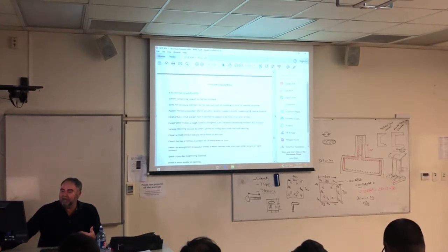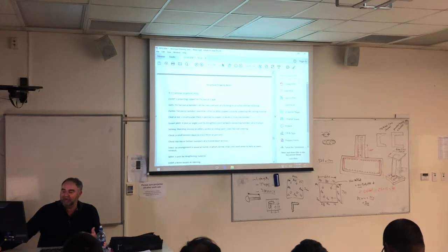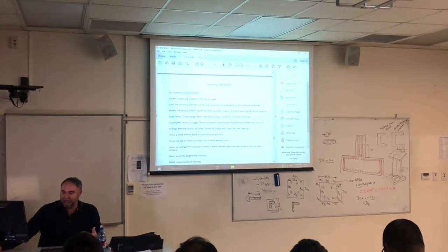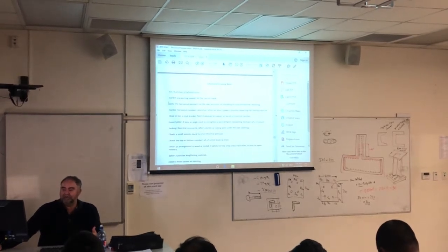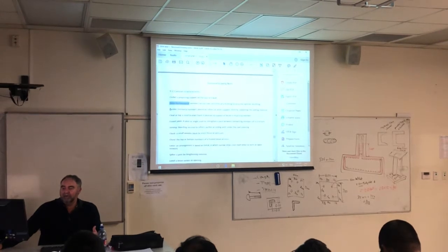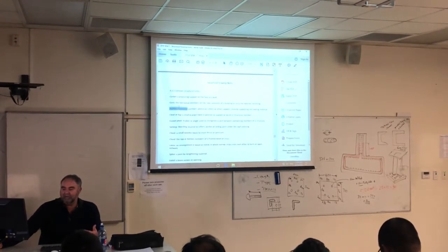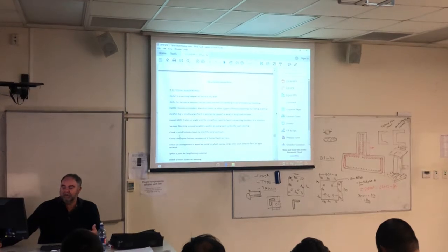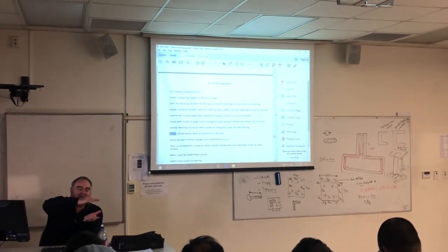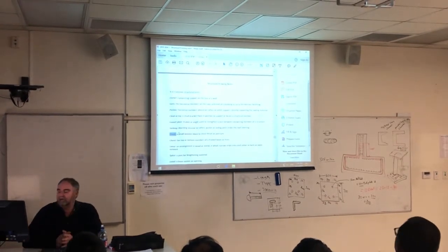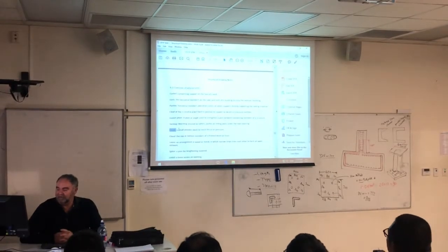Okay, we've got some common terms used in structural steel and some good explanations of what they are and where you would find them. The ones I've picked on for the multi-choice: girts, purlins, and a common Kiwi word, chock. Not chuck, chock. Chock is a small wooden block to resist thrust or pressure. So it's usually put between two other steel members and it reduces pressure.